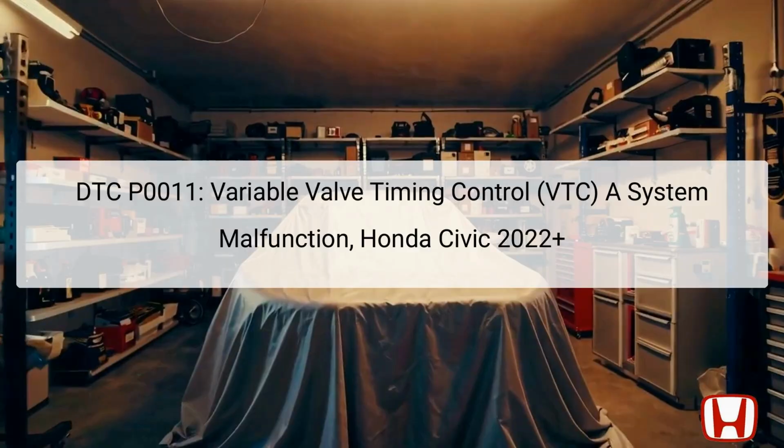The Diagnostic Trouble Code, or DTC, P0011 is triggered when there is a malfunction in the Variable Valve Timing Control, VTC system, specifically related to the A system. This code indicates that the phase difference between the command given to the camshaft and the actual position of the intake camshaft is beyond acceptable limits. The Powertrain Control Module, PCM, detects this inconsistency and stores the code for further analysis.